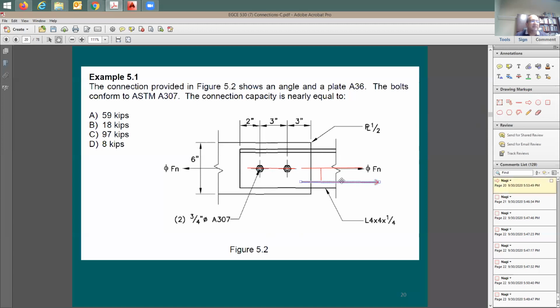So if you come at this distance, which is a spacing from the center of the bolt to this force, and you call it E. So I'm going to call this E, which stands for eccentricity. Let's say in inches. And this force, I'm going to call it here F. Now, how much is the moment acting on this assembly? You say the moment equals F times E. So we're going to have additional moment rotating the system this way.